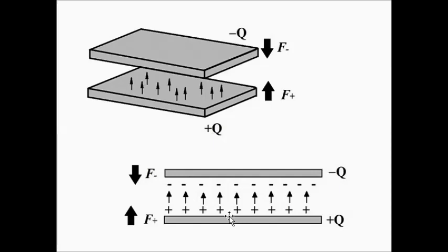So by mechanical movement of one of the plates, the electrical capacitance associated with the parallel plate capacitor will change. Okay, so mechanical movement causes a change in the electrical characteristics of the parallel plate capacitor. Okay, the movement is of mechanical nature and the capacitance is electrical quantity. So here mechanical movement causes a change in the electrical characteristics. So we are converting mechanical energy into electrical energy.